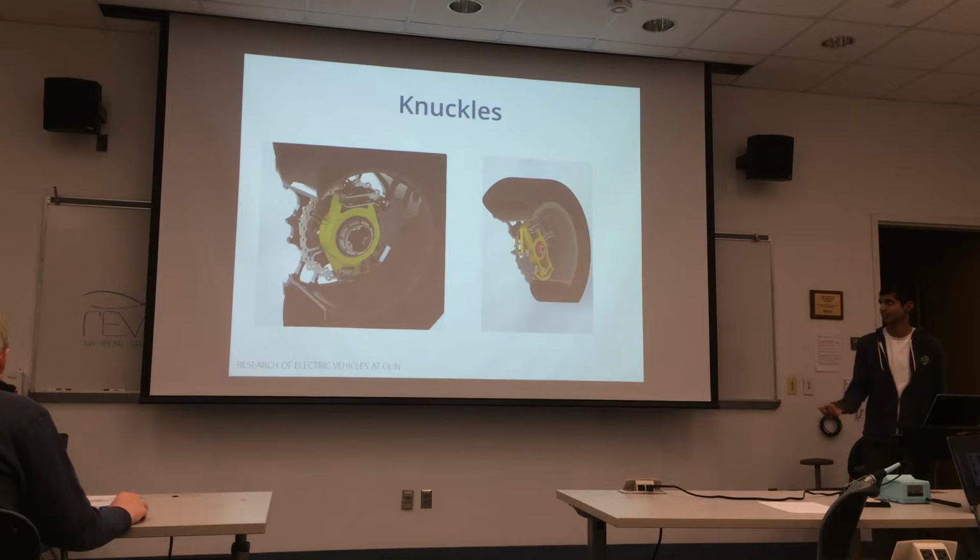The knuckles are a really key hub of suspension mounting. These attach to the two A-arms. This is what the wheel and the hub attaches to. The brake disc and everything mounts off of that. The steering, this is where you attach your half shafts. In case you're wondering, it's like the giant gold piece in the middle of both of those.